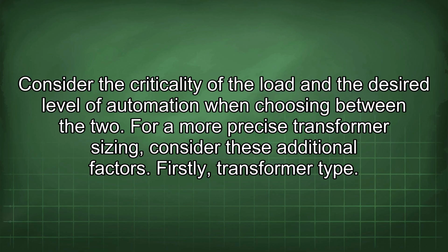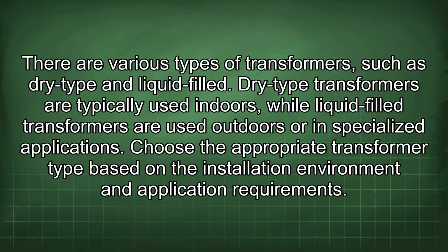For a more precise transformer sizing, consider these additional factors. Firstly, transformer type. There are various types of transformers, such as dry type and liquid-filled. Dry-type transformers are typically used indoors, while liquid-filled transformers are used outdoors or in specialized applications. Choose the appropriate transformer type based on the installation environment and application requirements.